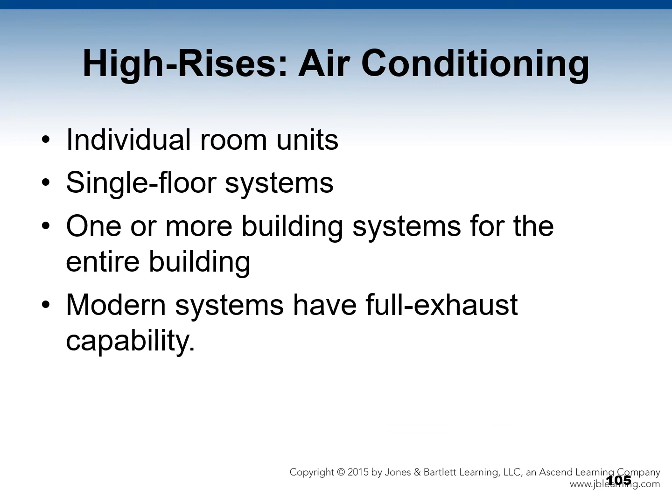Now let's talk about air conditioning in high-rise buildings. Individual room units that recirculate room air or draw air only from the outside will have no effect on the general situation. Single floor systems cause smoke from any fire on the floor to be distributed throughout the entire floor itself. Vents from the ducts may feed the floor above. When the entire building is air conditioned by one or more building systems, a giant HVAC system, any smoke from a fire used to be recycled through the building. But more modern systems often have a true full exhaust capability.